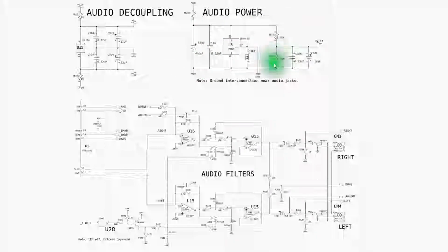these feed over to these two resistors here. They're 1.02 k ohms. They're both equal value, and basic Ohm's law tells us that if I have 5 volts across these two resistors, it becomes a voltage divider network. And I should see approximately 2.5 volts here. So it creates this AV reference of 2.5 volts. This has got a couple different filtering capacitors on it, again, to, I believe, deal with noise. There's a small cap and a larger cap. So we need to keep that in mind.